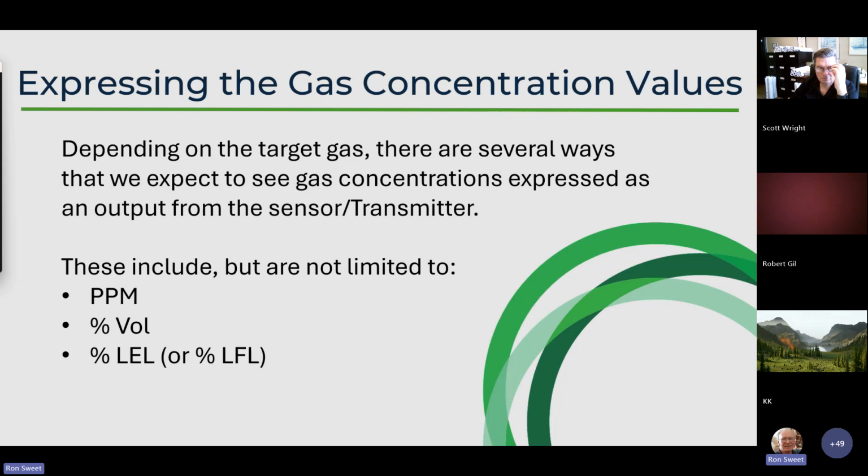So there is the lower explosive or lower flammable limit, and that goes all the way up to a concentration that is measured as the maximum upper explosion or flammable limit, UEL or UFL, at which above and beyond that, there's too much of that gas and not enough oxygen, so you're not going to have an explosion or a fire. But our concern inside a building envelope is not reaching the concentration of percent LEL.